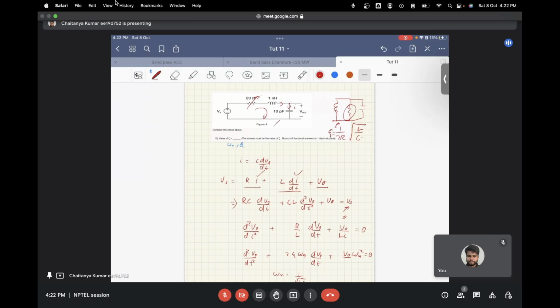And in the series RLC case, you need a 0 resistance to make the damping 0. So you can keep these things in mind, and also the values of the damping factor, quality factor, and the natural frequency for both the series and parallel RLC networks for quick calculations.